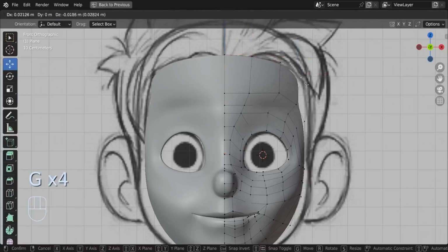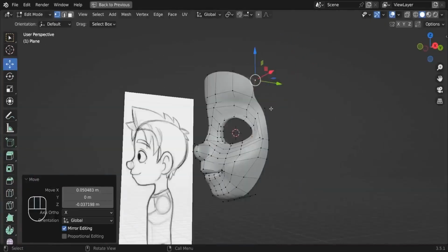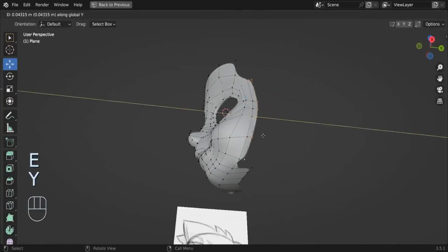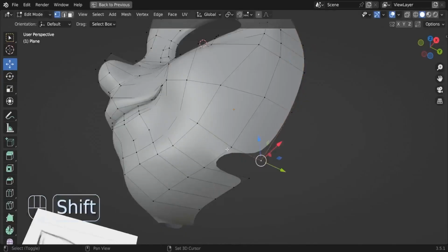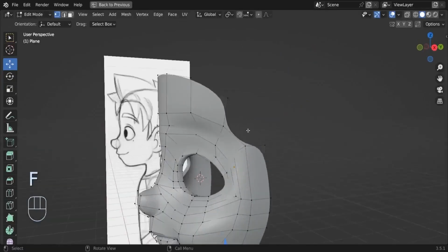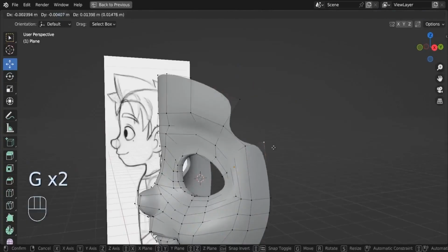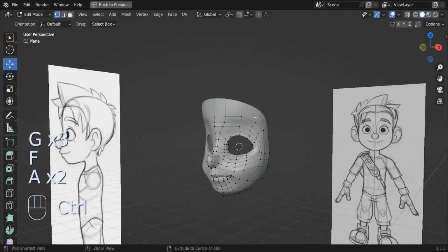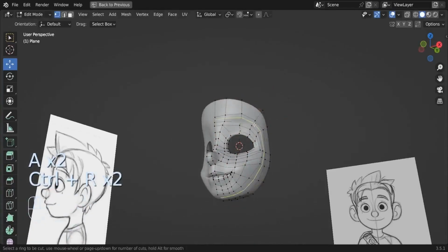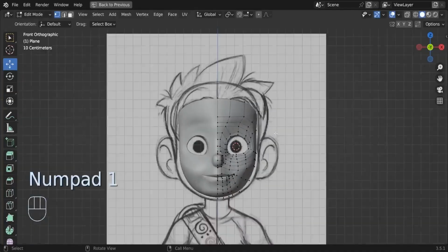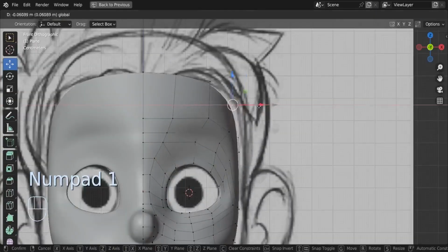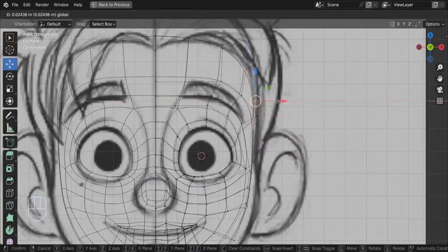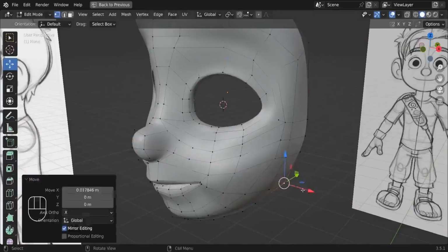You can select these 4 vertices, extrude them up till they reach the forehead. Okay, we need to finish that face loop. And here, for example, we can select all these vertices, extrude them on the y-axis. We can fill this gap that we got on the bottom. And here for the top, we can make these a little bit close and let's select them. Press F to fill. So now we're having the second edge loop. This is the first, this is the second edge loop. All right, so let's press 1. Obviously we have to slide those like this. We need to make our face a little bit circular, and that's nice.